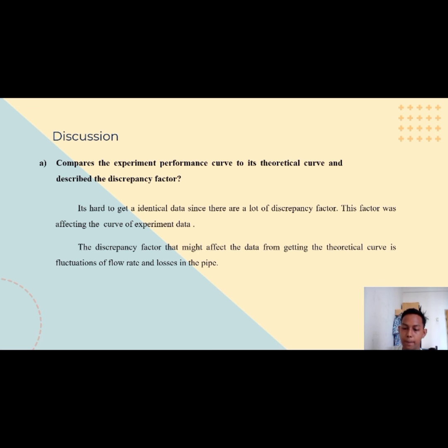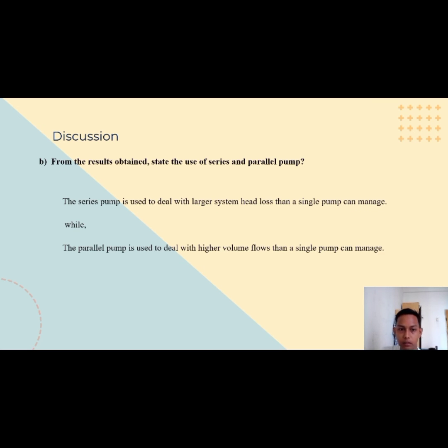The second discussion is, from the results obtained, state the use of series pump and parallel pump. So the series pump is used to deal with larger system head loss than a single pump can manage. And the parallel pump is used to deal with higher volume flow than a single pump can manage.